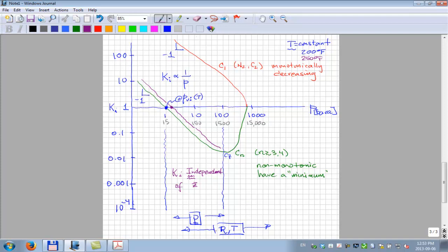And it's this range out here and how this high pressure behavior looks. That's what we're seeing mainly in the reservoir and in some of the production tubing where you have high pressures. Okay? There, heptane behaves differently in the Troll field, in the Qatar North field, in the Oklahoma City field. Behaves differently in every field. So that's this high pressure range out here. So out in this range, you have a relatively strong dependence on the overall composition.